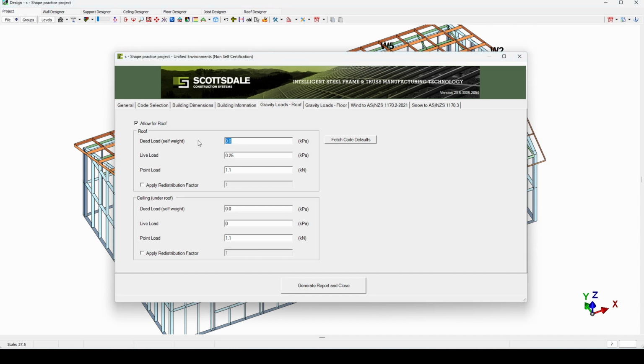Now, taking into consideration just a normal simple roof structure like having your trusses in there, or in the case of a roof panel with just some purlins, you would indicate what type of roof covering it would be, like roof sheeting like IBR or corrugated sheet metal, or you go to the roof tiling or concrete tile option, that would obviously indicate a larger weight added onto the structure. So for this case, I'm just going to use a simple weight of sheet metal roofing on top of purlins, on top of my panelized system right there. Generally, you go to about 0.2, 0.3, which would actually indicate about a 30 kilogram weight.